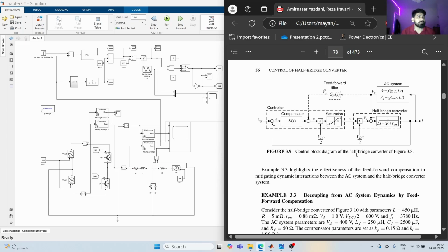We derive the system impedance through them. We have the short circuit ratios. These all are the information of the grid, and as much information as we can have of the grid, how weak it is, how strong it is, how it behaves, how the damping characteristics are, we can feed this information to our controller, give it more information, make it more efficient with this information, and get very efficient results like what we saw in our model.